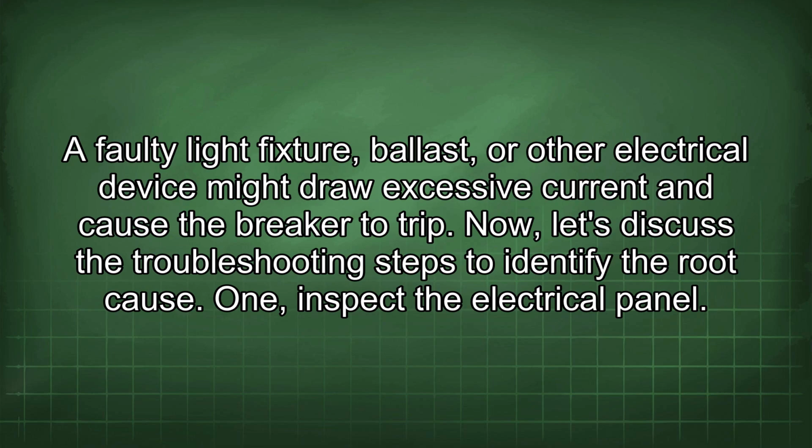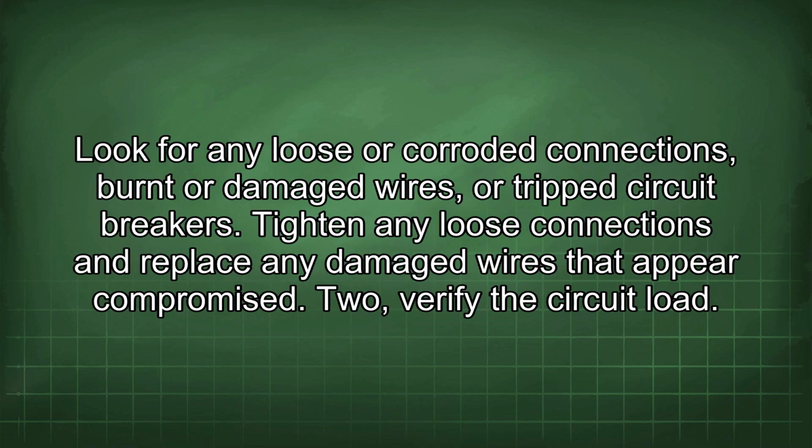Now, let's discuss the troubleshooting steps to identify the root cause. 1. Inspect the electrical panel. Look for any loose or corroded connections, burnt or damaged wires, or tripped circuit breakers. Tighten any loose connections and replace any damaged wires that appear compromised.